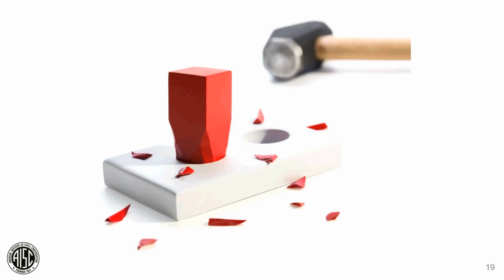One thing I wanted to caution you about is over-specifying material. Well, over-specifying material is sort of like taking a square peg and trying to put it into a round hole. You have to chip sides off of that square peg in order to get it into the round hole. Every one of those chips is money. So what do I mean by over-specifying material? Such as requiring Charpy V-notch testing of all material, even though it's not required. Specifying 70 ksi material, even though 50 ksi material might work. Even specifying atmospheric corrosion resistant material when it's not required. So don't over-specify material, because if you over-specify it, it'll still meet the strength requirements or the requirements of your design. But all those chips cost money that you don't want to have to expend if you don't have to.